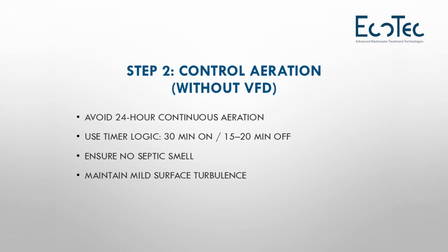Let's understand the dissolved oxygen-based operational problem. This is where serious misunderstanding exists. Dissolved oxygen-based operation has been promoted as smarter control or even smarter operation. But DO does not measure biology. It measures dissolved oxygen in water. In low load conditions, oxygen demand is not so high.